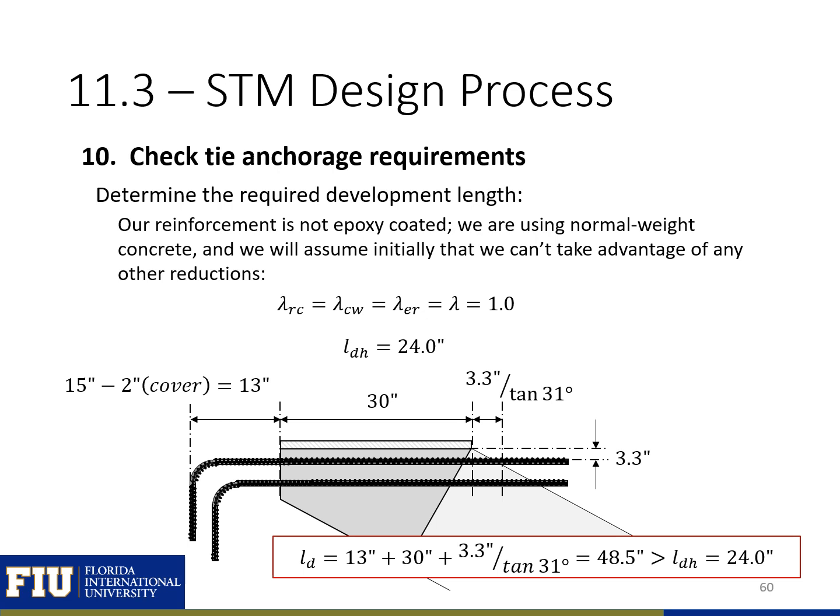Our reinforcement is not epoxy coated, and we're using normal weight concrete. So we're going to assume that, and also we're going to assume that we can't take advantage of any other reductions, just conservatively. So our development length will be equal to 24 inches.